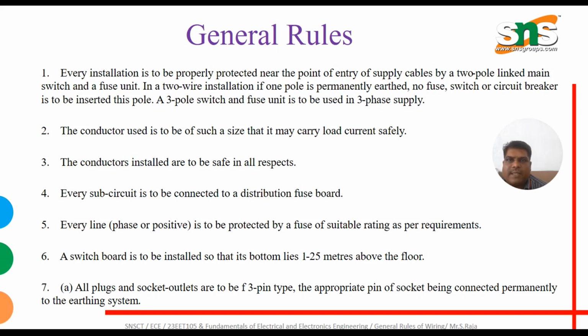In a 2-wire installation, if one pole is permanently earthed, no fuse, switch or circuit breaker is to be inserted at this pole. A 3-pole switch and fuse unit is to be used in a 3-phase power supply. If you see in our classroom, the students are inserting a mobile charger in a 3-phase without knowing that it is 3-phase. So 3-phase means you have to insert only a 3-phase cable, like a charger cable or a projector cable. Likewise, you need to insert.